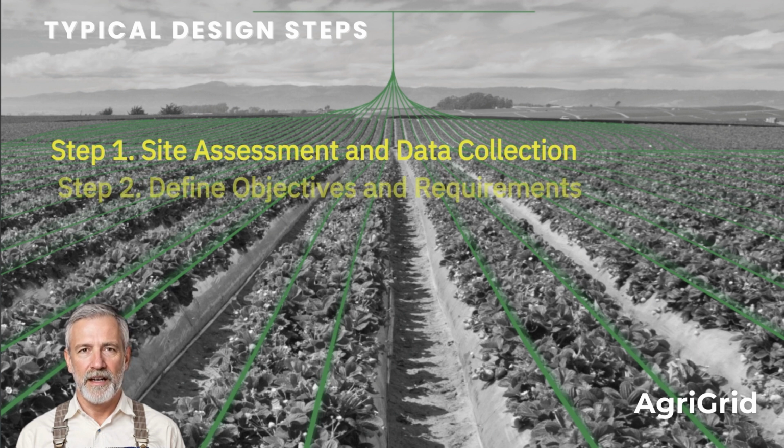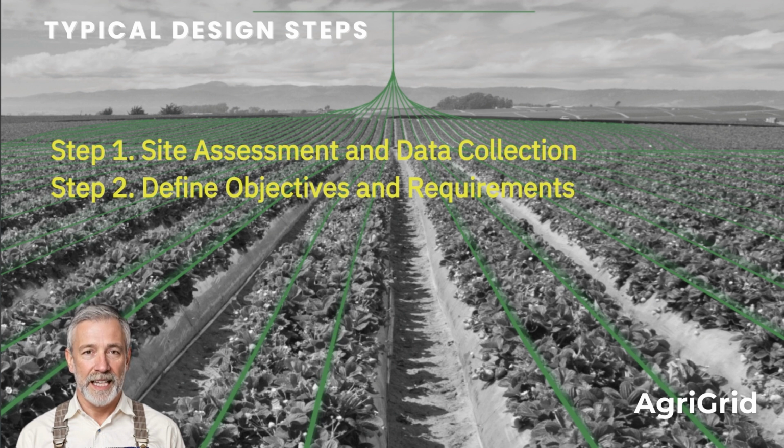Step 2. Define objectives and requirements. Purpose. Establish the goals of the irrigation system. Clarify the purpose such as agriculture, lawn maintenance, or garden enhancement. Then calculate water needs based on plant types, growth stages, and local weather. Set priorities like water conservation, cost efficiency, or automation.